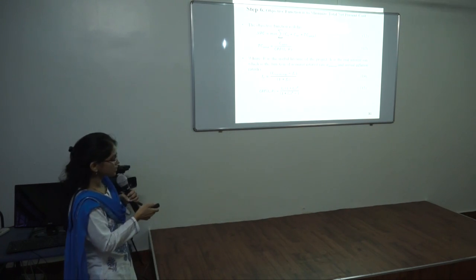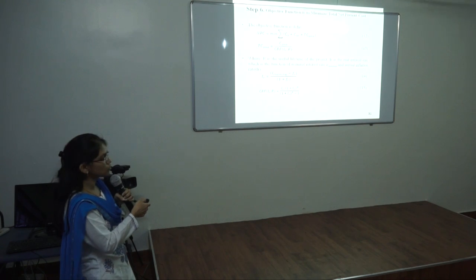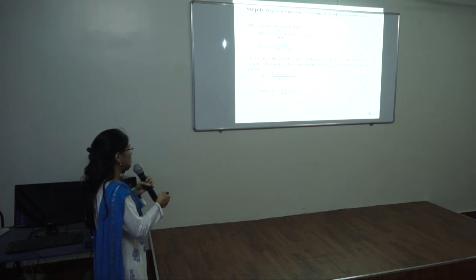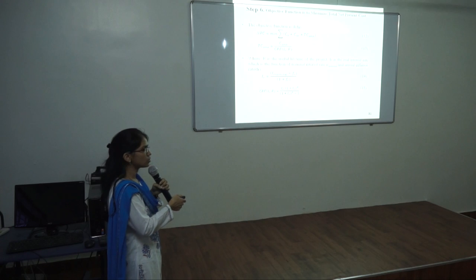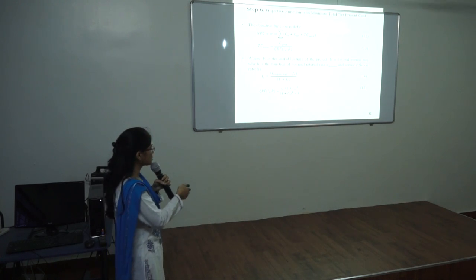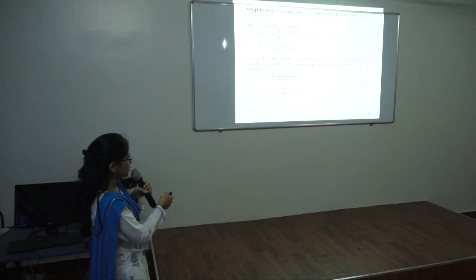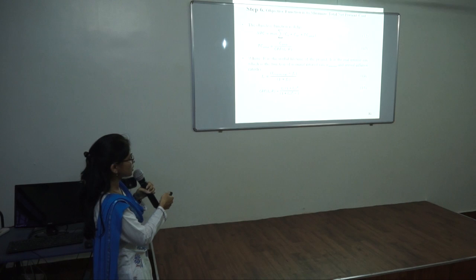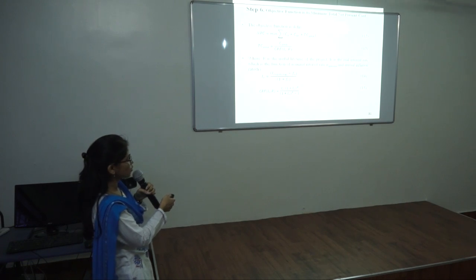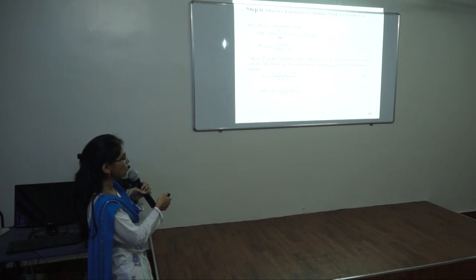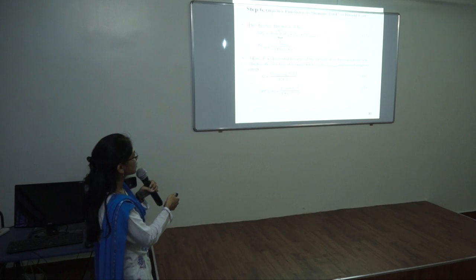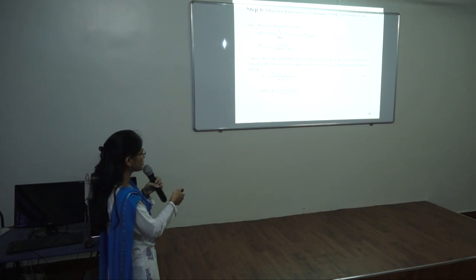After selecting the system components, the next step is to define the objective function. In this study, the objective function is to minimize the total net present cost, and it can be calculated by using equation number 12. The net present cost consists of capital cost, replacement cost, and operation and maintenance cost of all components which are used for the design of the hybrid system.